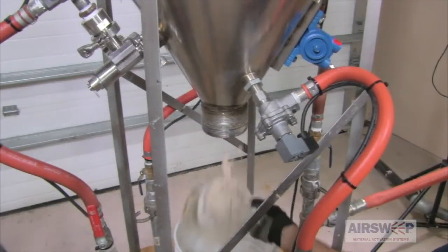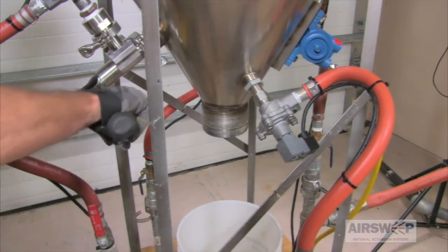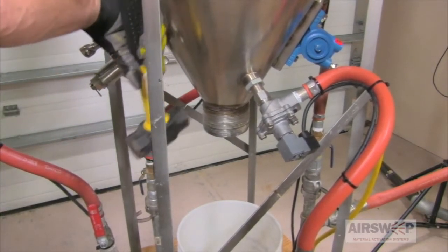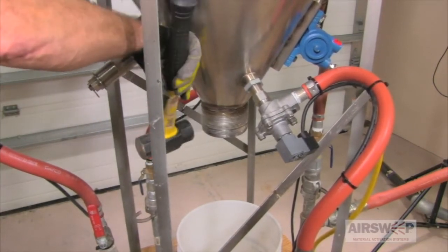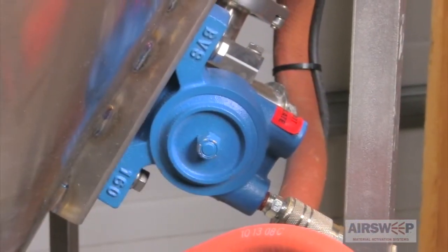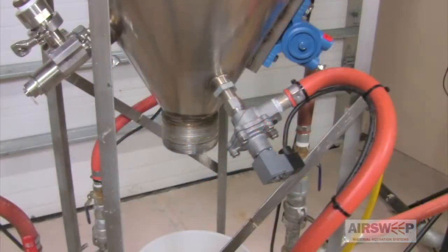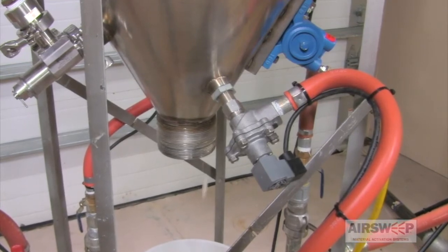When the discharge is opened, no material starts to flow, so it's clear a flow aid of some kind is needed. First up is the dead blow hammer, which doesn't produce flow. Now the vibrator is started up. One vibrator mounted as shown is a typical configuration for a vessel of this size, but it also is not producing any steady, significant flow from the hopper.